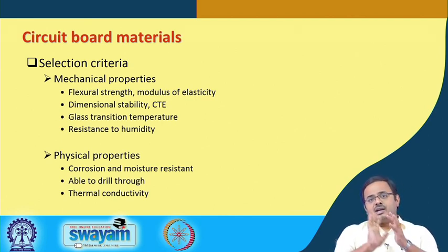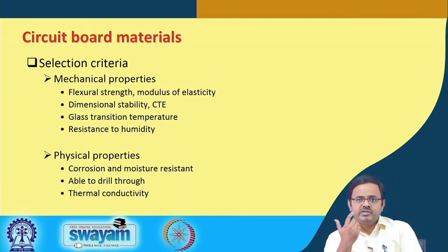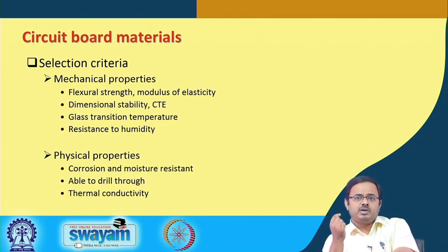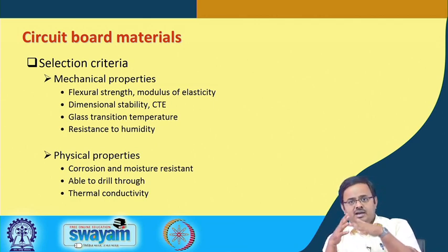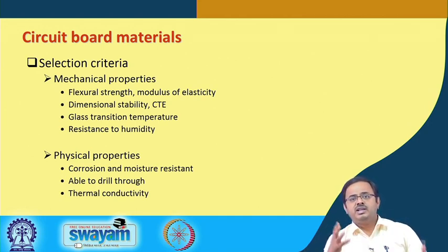And finally, thermal conductivity, it is a thermophysical property, extremely important, because from the point of view of heat dissipation. Okay. The component is going to generate heat, and that heat has to be conducted through the motherboard. A lot of that heat, if I can conduct it through the motherboard, then it will help me in maintaining the temperature below the acceptable limits.